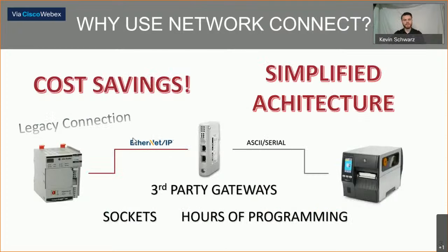So why do we want to use it? First and foremost, there's a huge cost savings associated with using this NetworkConnect firmware, as well as it simplifies your architecture when you're deploying it in the field. Where you see your cost savings is that the old way of communicating from a printer to a PLC, you had to have a third-party module, which would run you in the neighborhood of $500 to $1,000, and you also had to have the programming costs associated with it.